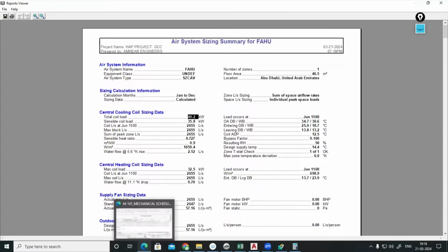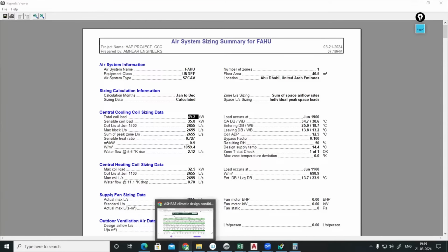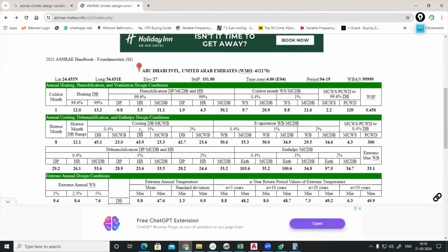When you are doing projects in high humid conditions, especially in Gulf conditions, for air conditioning machine selection we can use this value. For ventilation equipment and cooling tower selection, we will be using this value. For evaporative cooling, whenever we are dealing with more atmospheric air, there we will be using this value. Okay, because there the relative humidity will be high. Instead of sensible heat, latent heat in the atmosphere will be more. That we have to take into consideration.